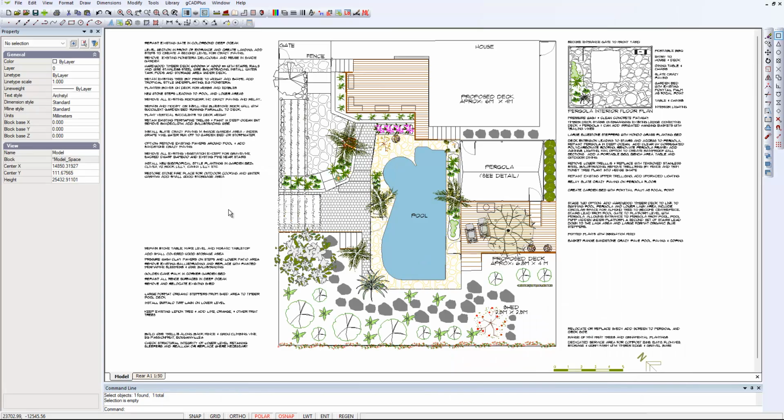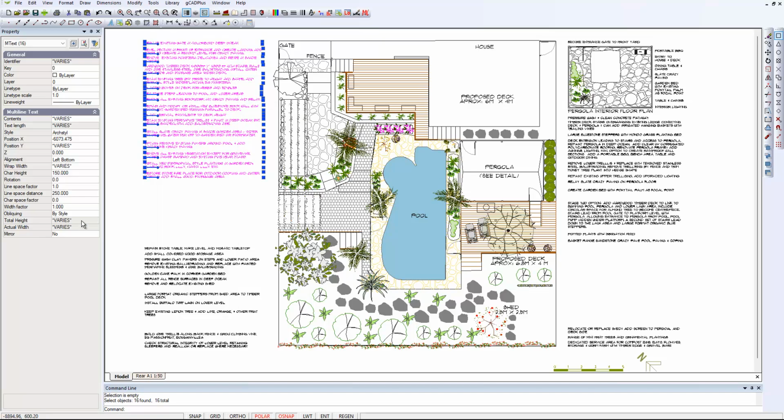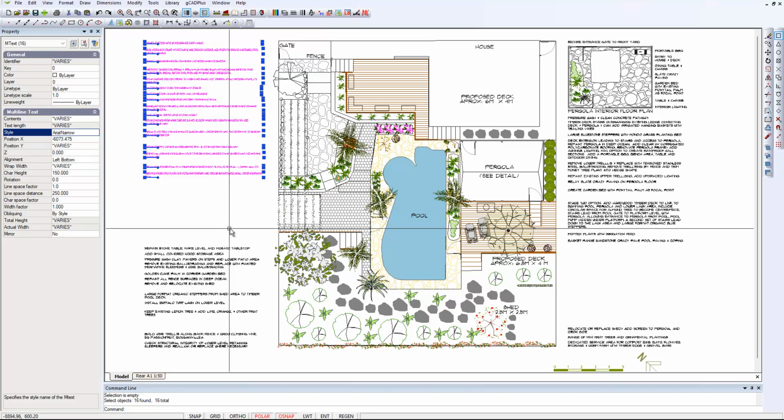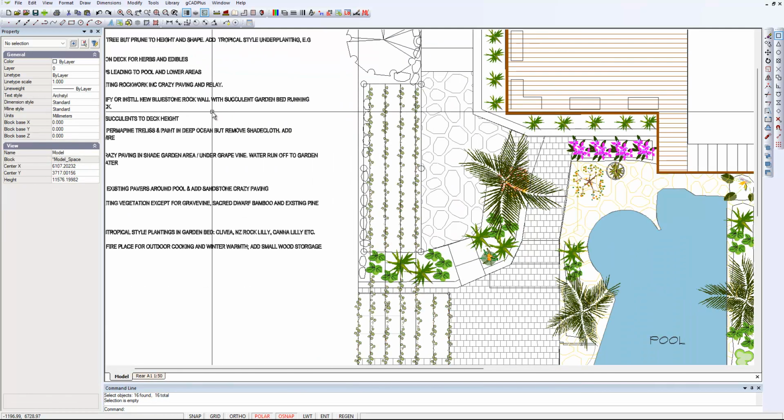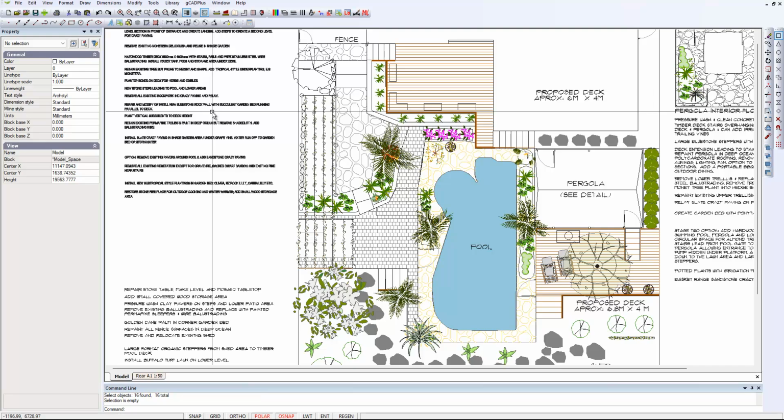So we've selected and tested that handwritten CAD font here. If we grab a whole pile of those and go across to style here and change from Arc Style to say something like Arial Narrow, then the spacing may be wrong, the height might be wrong, and you can see the effect here if I zoom in. It is much better to test and then settle on your font and spacing and then stick to it rather than decide to change, say, at this late stage of the game.